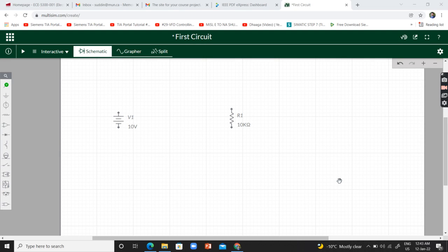All right, so we were at this point, we were about to interconnect our terminals. So we will just hover our mouse over this node, click on this part, and just remove your finger from the click, right? It's already picked the starting point. When you bring it back to over here, you can see that there is a circular zoom-in sort of transition that will appear. That means that your connection can now be made properly, right? So you can left click the mouse and that will establish that connection properly.